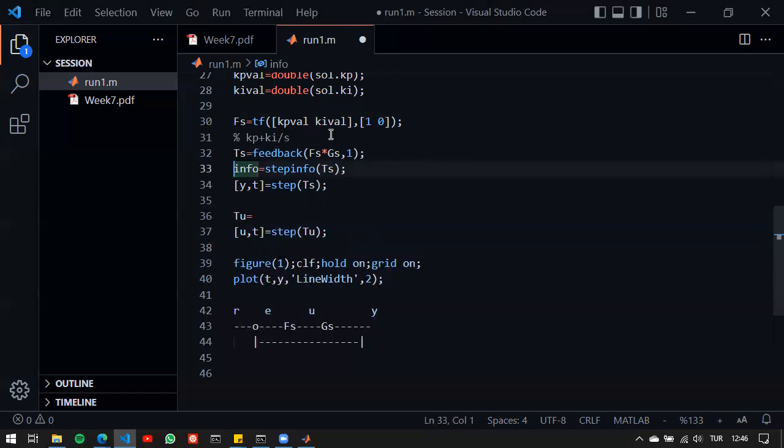So, yeah, we have a dynamic controller, which means that it's nothing constant here. Well, eventually maybe it's constant, but during the transients, we'll have dynamic behavior. And the transfer function of the controller, since we are using a PI controller, is Kp plus Ki divided by s. So what does this produce, basically, is the question here. So any ideas? How can we determine, or what is the transfer function Tu here?